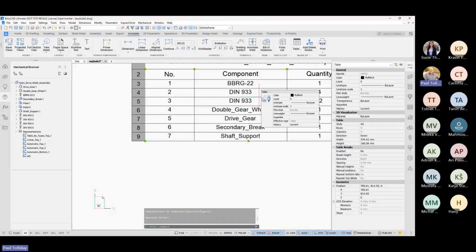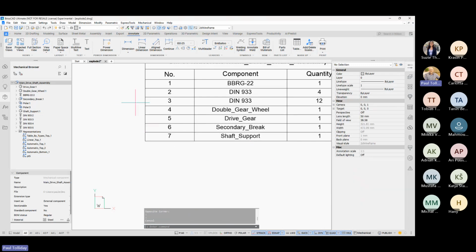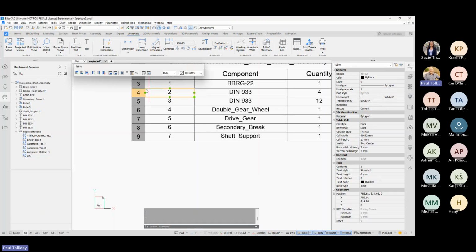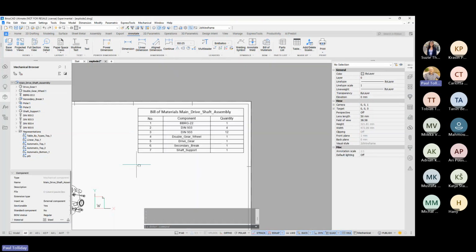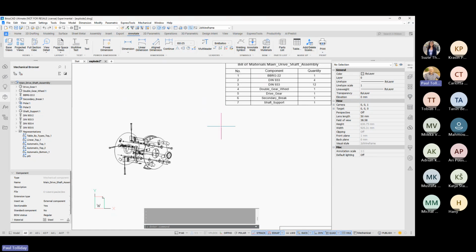The parts list can be edited in the properties as before. So you can choose the direction of the components, the size, but it shows all of the parts, some of the parts, sub-assemblies, top level, etc. Now we've got that though, we can go back to our bill of materials area and we use the drop down and we can either balloon single components or we can say auto balloon. This gives us some options.